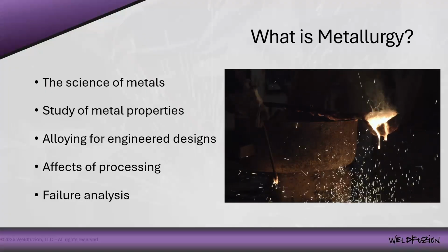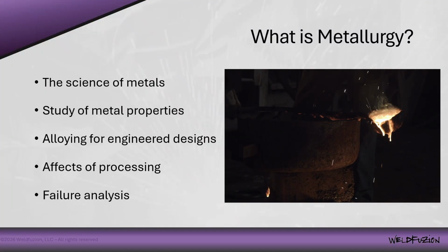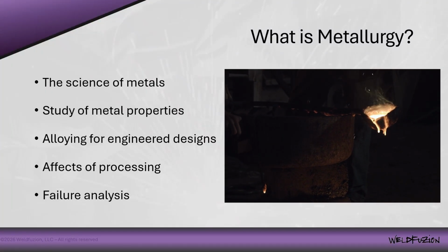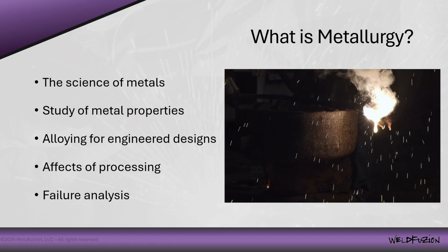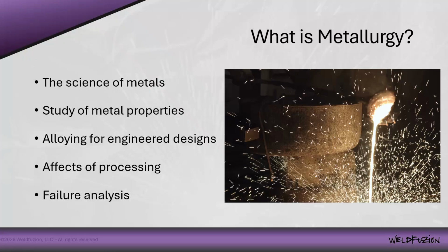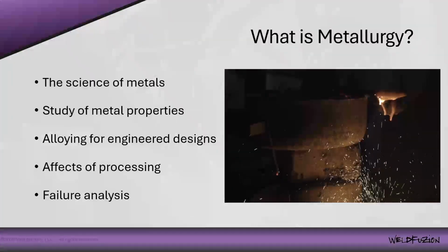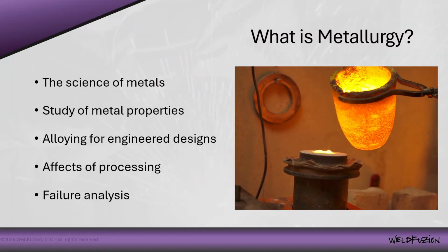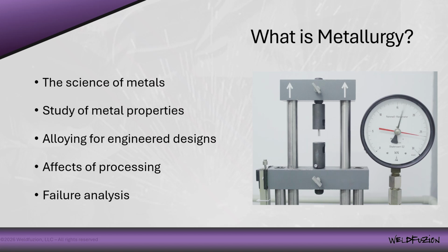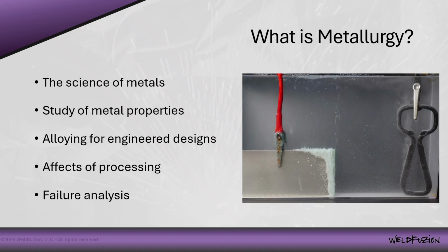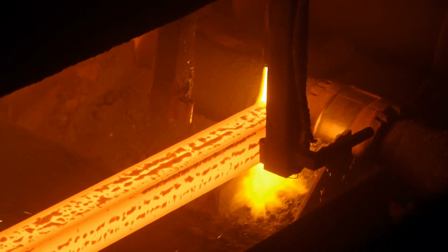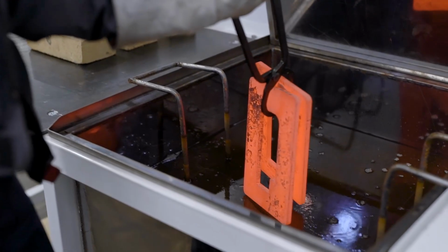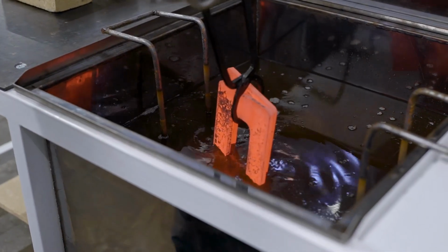Mixing metals with other metals and even non-metals is called alloying, a process that's done to improve different properties, and we'll dive into more on that when we discuss each specific alloy in the modules. All of the processing, alloying, and working results in key metal properties, mechanical, physical, and chemical traits that factor into welding. These properties are a combination of the mixture along with the heating and cooling rates used to process the metal. Heating and cooling at different rates can change these properties.